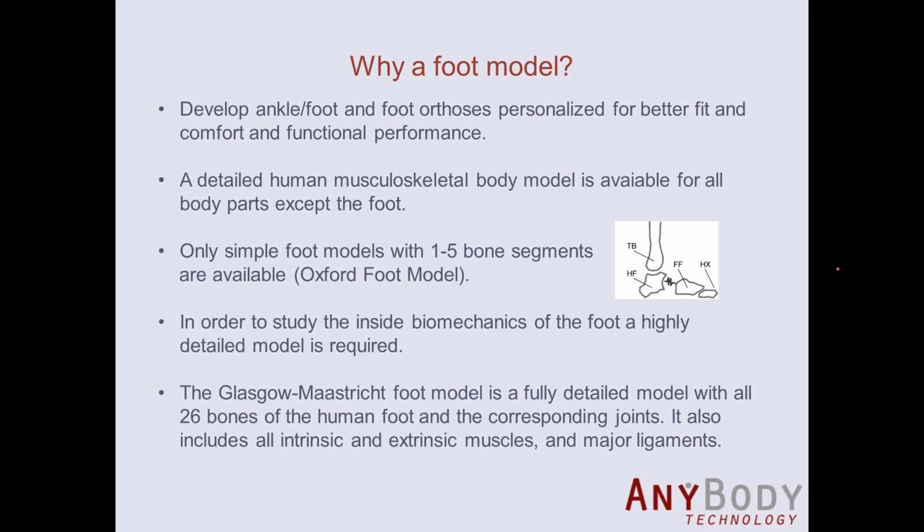This was not the case of the previous foot model we had. It was stiff, and the other foot models we can find in the literature are usually no more than 5 segments, so that's not enough for our purpose. That's why we are coming today with the Glasgow-Maastricht foot model, which is a very detailed model with all the 26 bones of the human foot, the corresponding joints linking the bones, and also intrinsic and extrinsic muscles, and all the major ligaments.